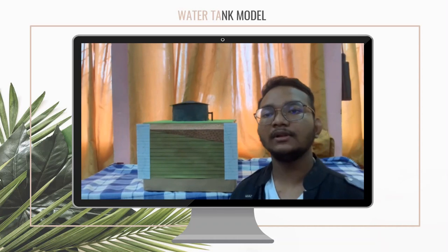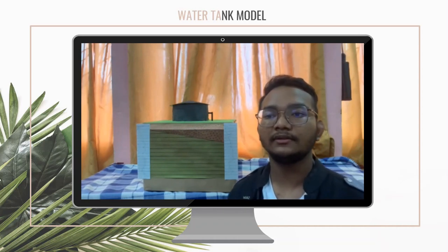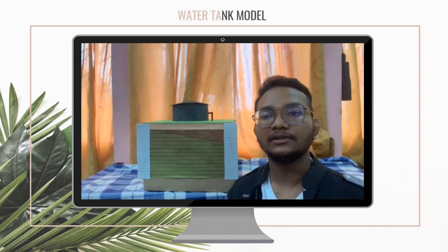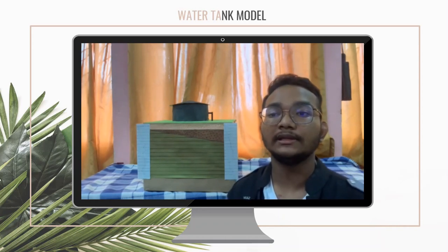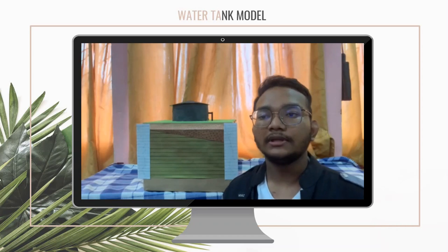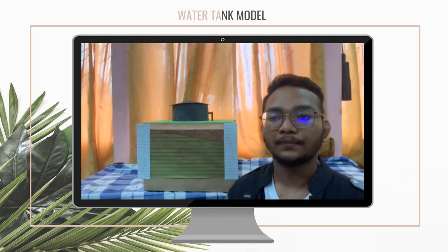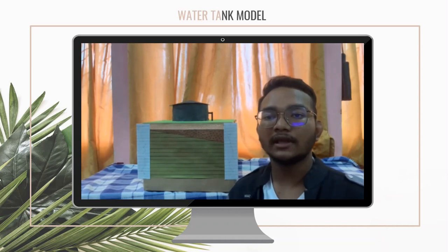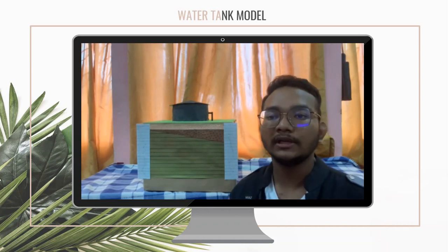Borehole 2 is unstable because it contains clay soil at a depth of less than 0.3 meter. Clay soil in general contains more space between its grains, allowing it to absorb more water. The soil will expand when it becomes soaked because of its ability to absorb water quickly.